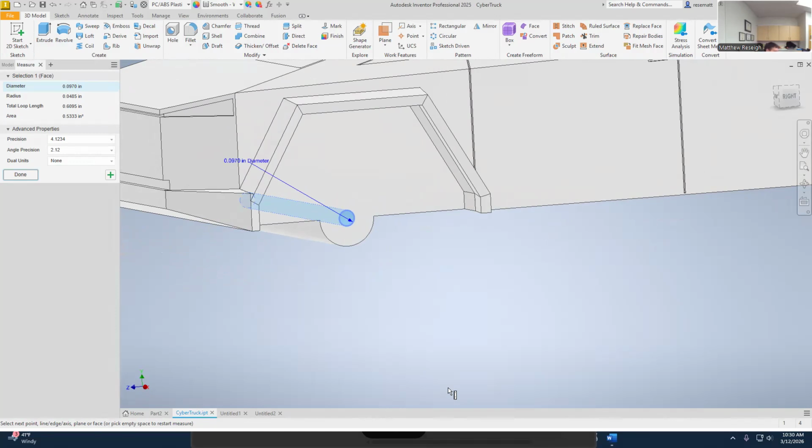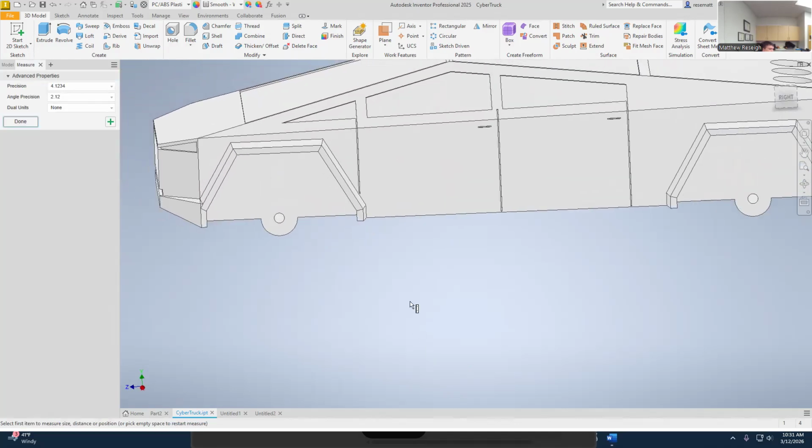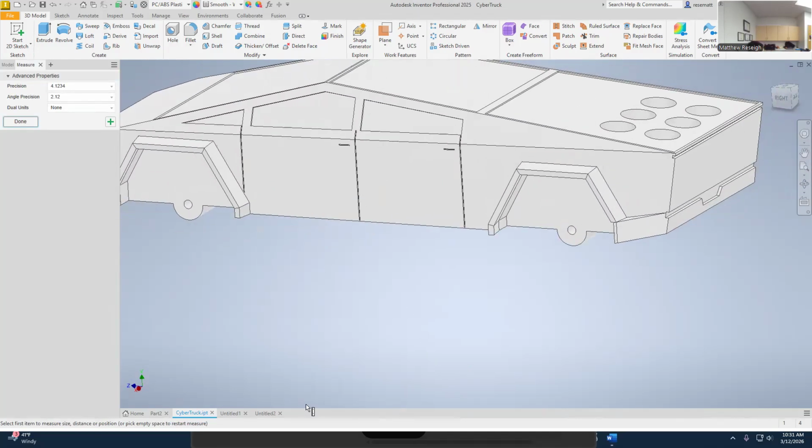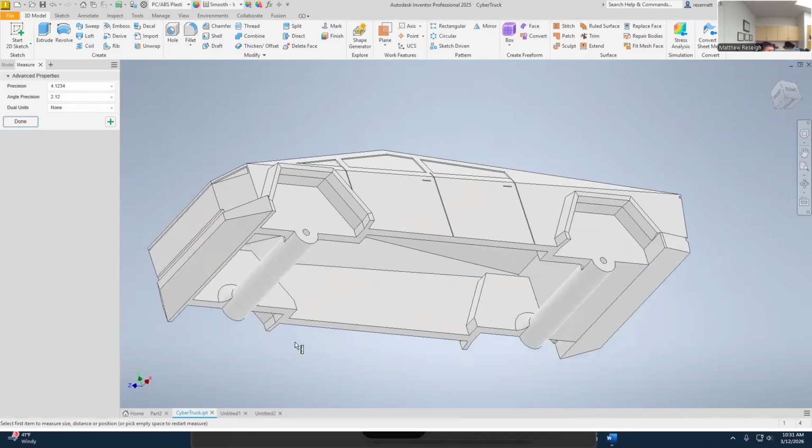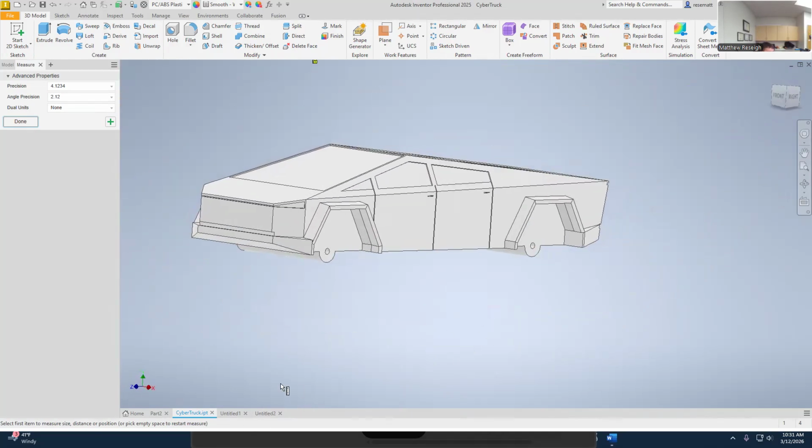You can glue them in, of course, but because I like to bend my axles, I like to be able to rotate those. So I don't really want to glue mine in until I make sure it's aligned and running straight and riding the rail just slightly. So I tried to keep the interference fit to where I could still make some adjustments to my wheel clocking, I guess you would say. Yeah. But I journaled this, and that's my engineering notebook. So that's why I wanted to show that last little bit on the video.